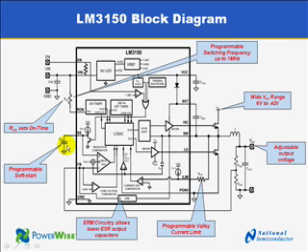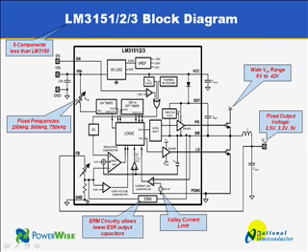As the device is able to supply up to 12 amps of output current, it needs an external soft start capacitor to program the soft start time. This prevents an overshoot of the output voltage during the startup. This resistor sets the on-time of the constant on-time circuitry, which actually programs the switching frequency of the controller.